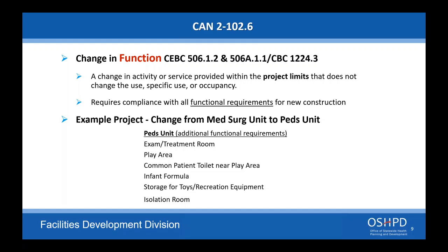Great. We got a lot of questions for the alterations, of course. The next question reads, during an alteration with no change of occupancy or use, if there's an electrical, mechanical, or plumbing system that only passes through the renovation area, for example, a TI, that is not compliant with current code, does this system need to be modified to meet the current code? In the above example, the system is not used within the project scope, but only passes through. And the general answer is no, you do not need to upgrade it.